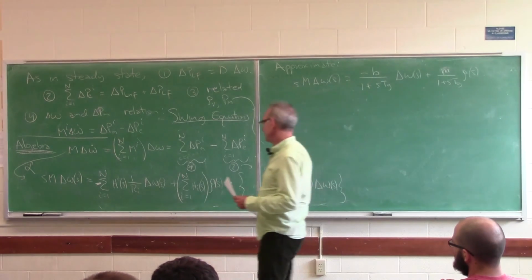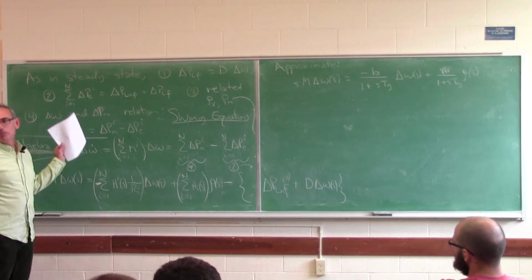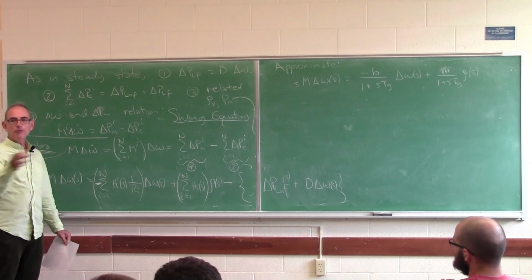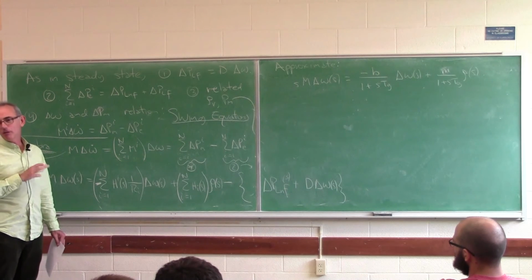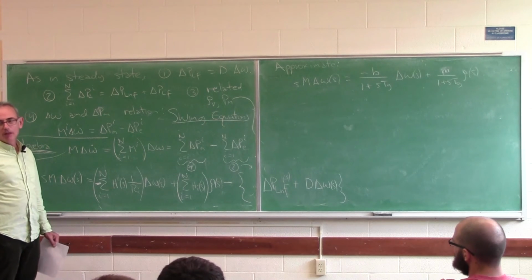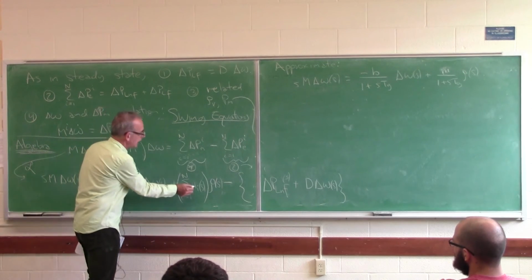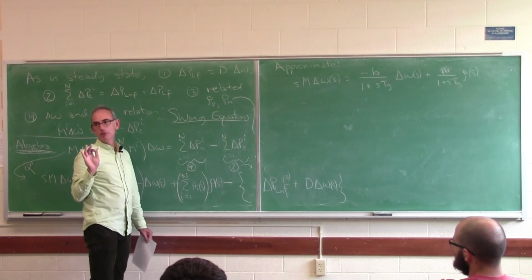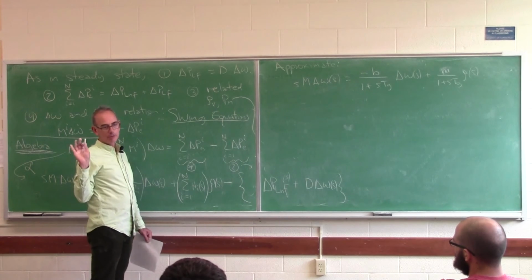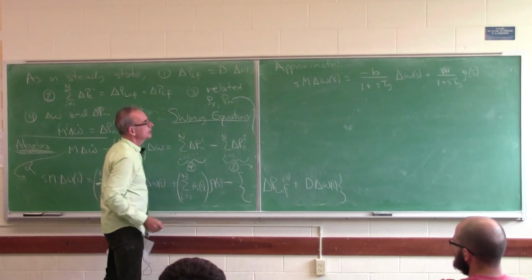Okay, so this complicated-looking transfer function, I'm just saying pretend it's first order, which means I've ignored valve dynamics, and I've assumed all of the droop dynamics are the same. They all have the same poles, which is an approximation, but not too far off. And here again, all of these have exactly the same pole locations, and we're approximating by first order, assuming the valve dynamics are fast compared to the droop dynamics. And that's reasonable as well.